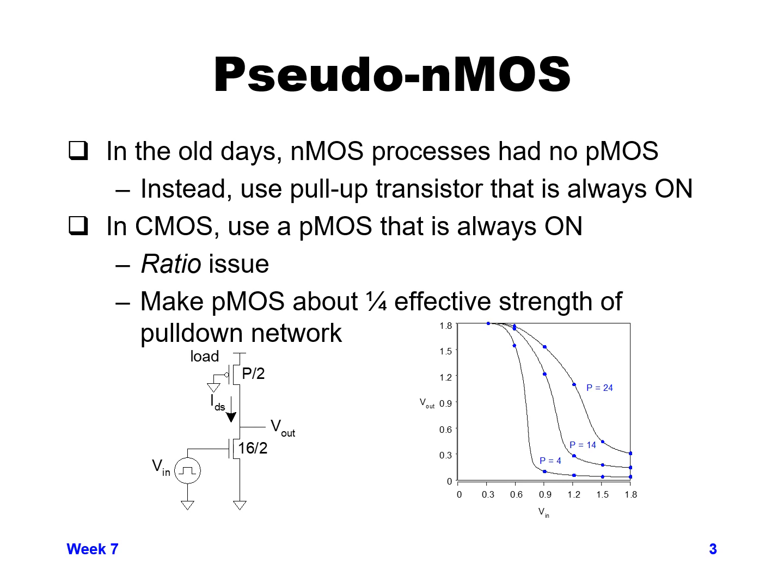And if we have the VIN going to the NMOS device, and if VIN is low, so the NMOS device is off, then that PMOS device is going to pull the output V out all the way up to the rail. But if VIN comes in and it goes high, it turns on the NMOS device. The NMOS device is a lot larger and stronger than the PMOS device, so it's going to try and pull V out down to 0.